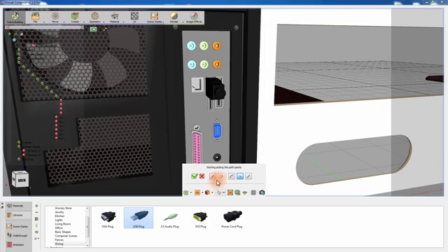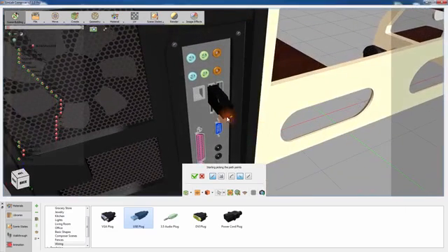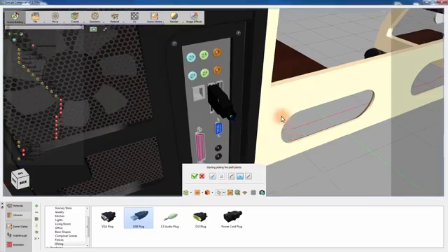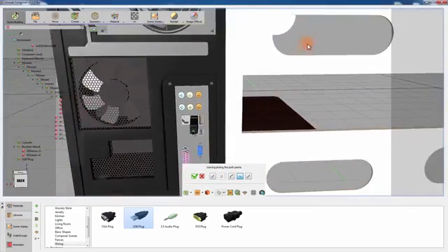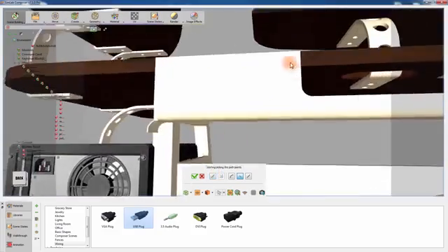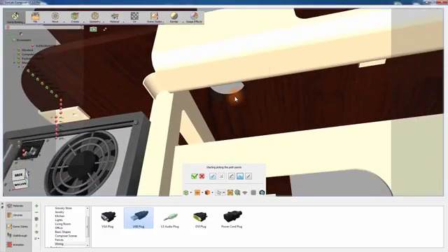Enable the Apply Tangent while picking option for the first and last point when creating a wire to make sure that the wire ends are erect. Click on one of the USB plugs to place the first point in the path. Disable the Apply Tangent while picking option and click on the created hole to add another point on the direction towards the mouse.